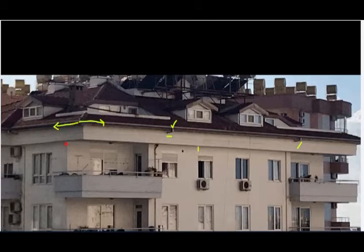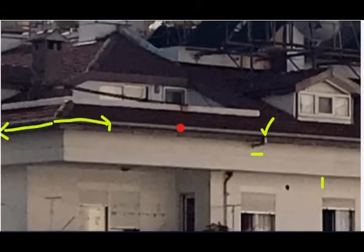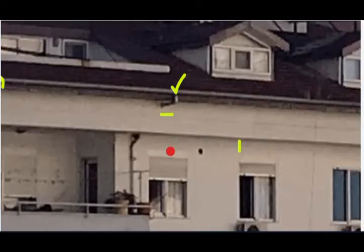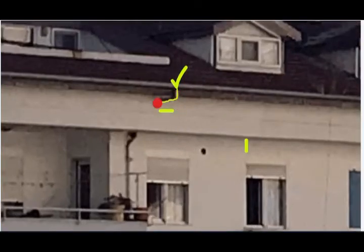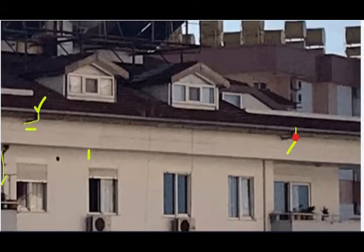My suggestion is to put 3% of slope, not 1.5. And the reason is that the faster you manage to take the water down the pipe, the easier it will be for you, and this place will not be dirty in the future. So if you look at here, the pipe is coming from here, going to the other side, and then coming to the wall. This is very important. Again, look at here, coming down.